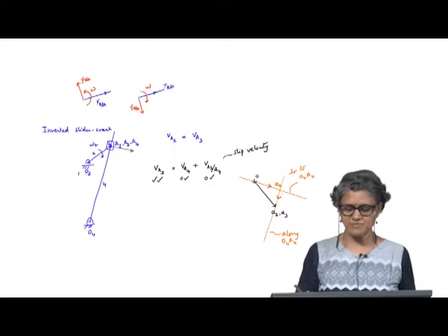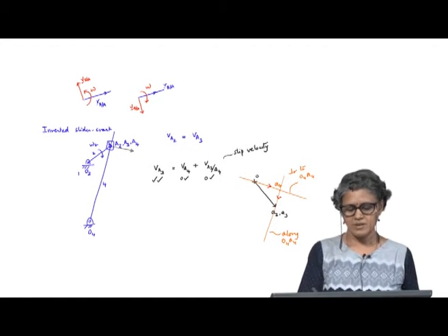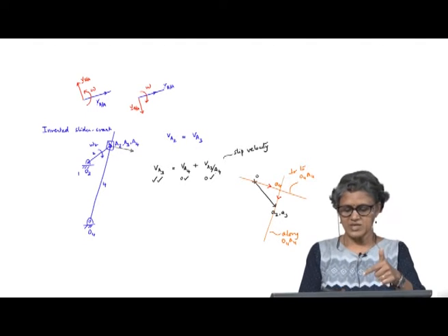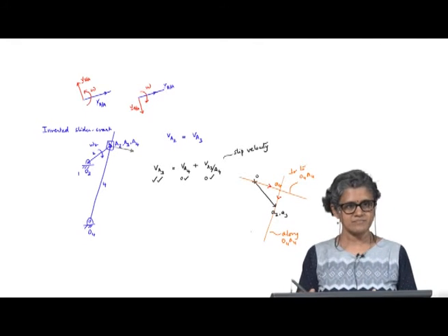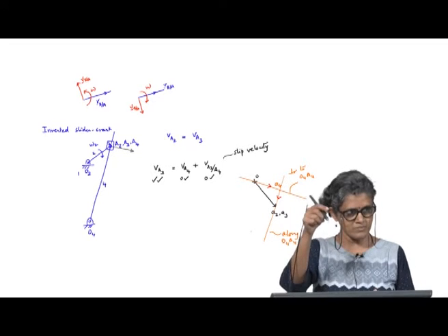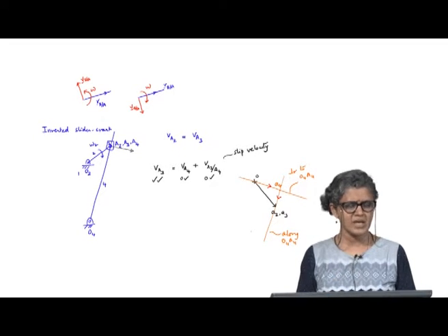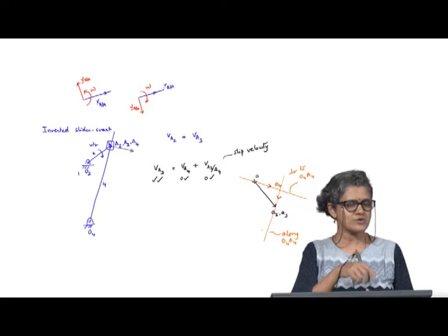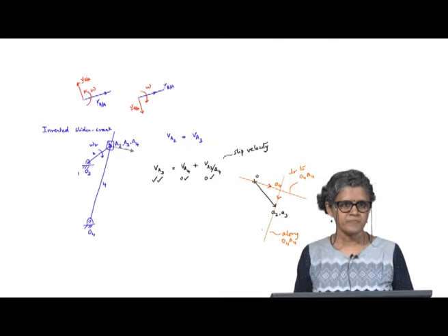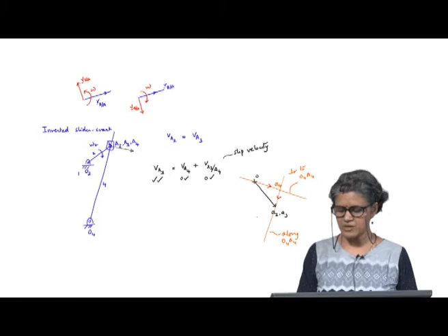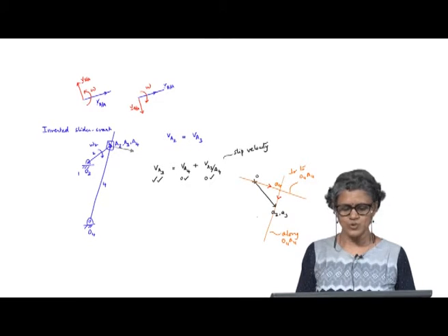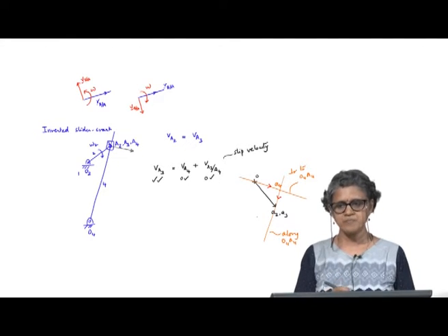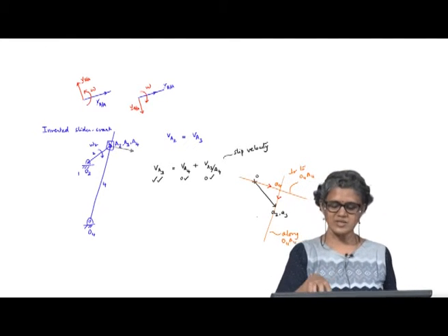Okay. So, my slip velocity, so A on body 3 is moving in this direction from A on body 4, which, as you can see, because of the clockwise rotation of the crank, makes sense. So, it is moving away from that coincident point in this direction. Okay. So, this is how you do the graphical velocity analysis when you have a sliding joint, and this velocity will become important